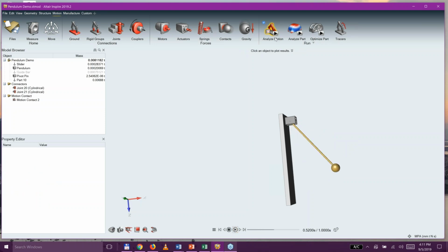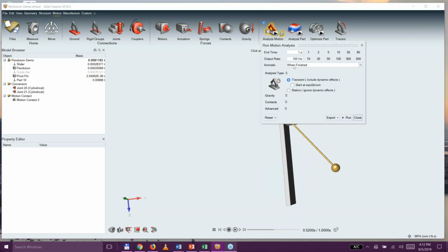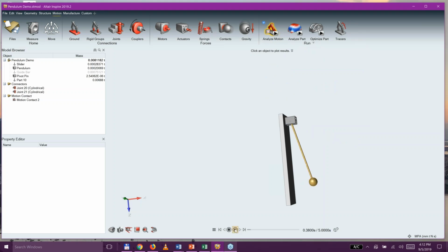And if I were to instead now come here and change my optimization parameters, let's go down to 50 so it doesn't take long. And let's run this for 5 seconds instead of 1. So it'll take a little bit longer because I've got 5 seconds. And you'll see every once in a while it's going to pause a little bit. More than likely, each one of those times that it's pausing, it's having to calculate a new contact, because now when I run this, I can see the behavior of that slowing down.